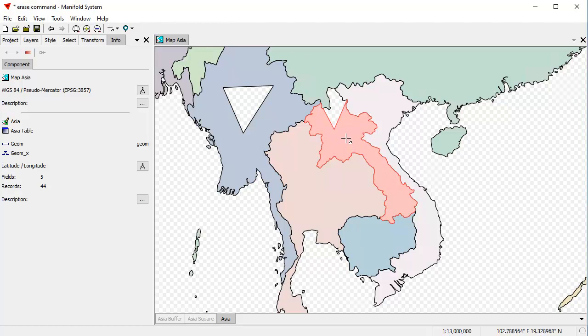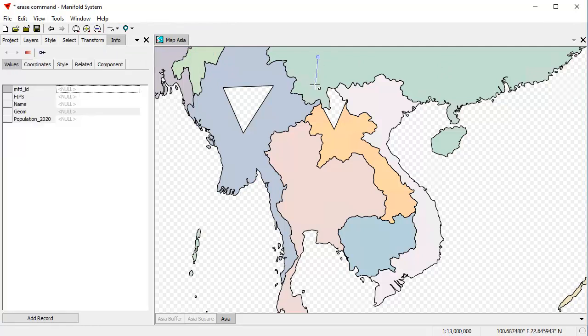Let's Control-Shift-Click that to deselect that. And we can also use arbitrarily complicated area drawings. For example, we can click, click, click. Let's create a multi-part area here, and I'll shift-click here to stop that branch. Now I'll click another island here. As you know, if you're into GIS, multi-branched areas can have island shapes, and there's another one. And let's click here, here, here, and shift-click there. I'll shift-click there. And now here, let's create a hole in it, which will create a kind of donut-shaped area object. So we'll have one island here, one island there, and the donut-shaped object here.